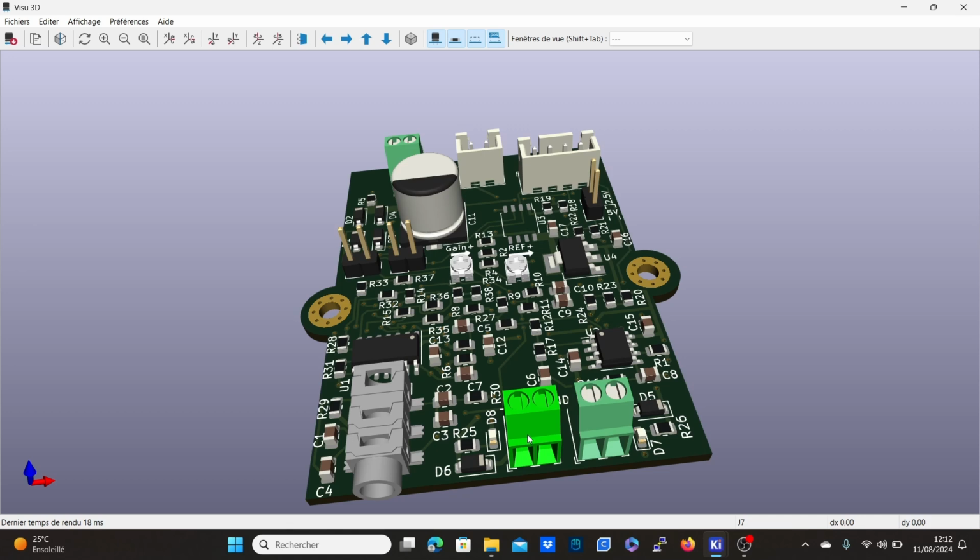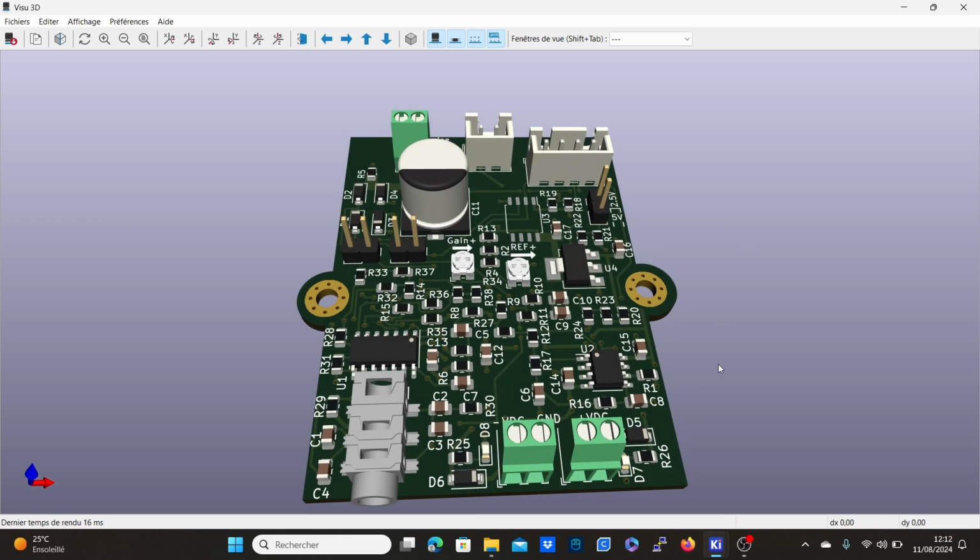You may have to do some research, find another way of calling your component so that it comes out. And yeah, that part can take a lot of time. But once you make sure that all the components that you want for your PCB are available, you can start routing the PCB.